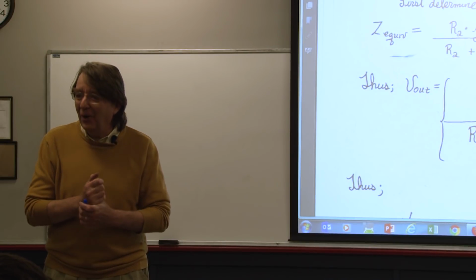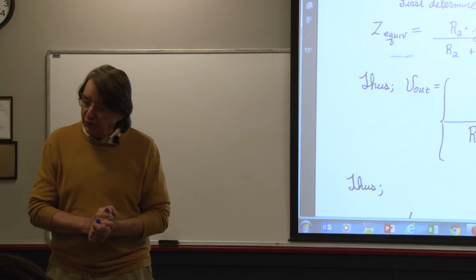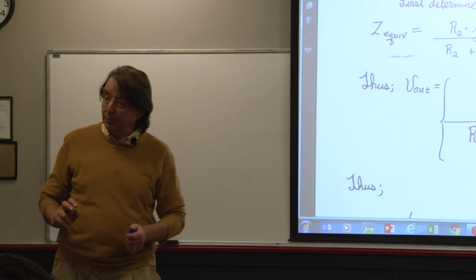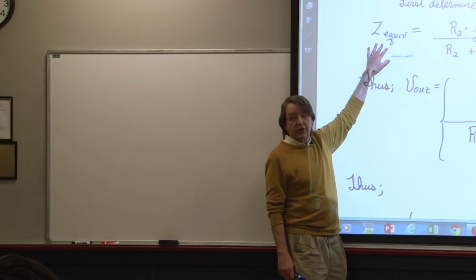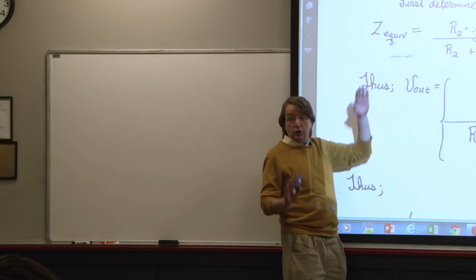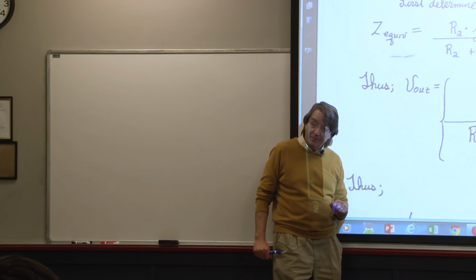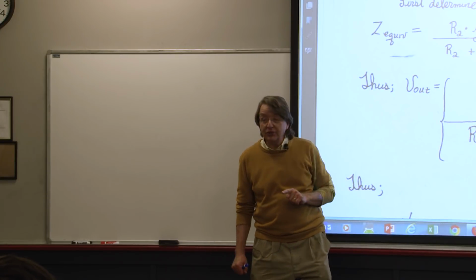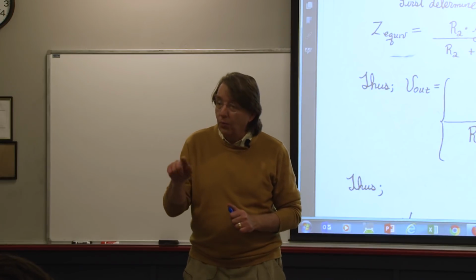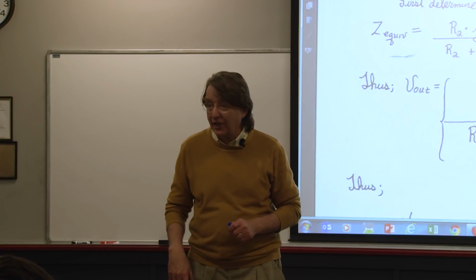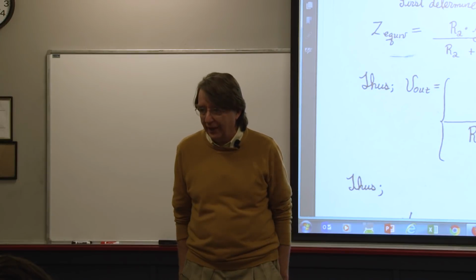Okay? So just follow through on the basic principles, Tara. So we use voltage division. And to use voltage division, I first have to get a ZEQ. So let me pause. How do we do? The short answer to your question is L over R is only valid if there's one R and one L. Here I've added a second R, so there's some other factor going on here.